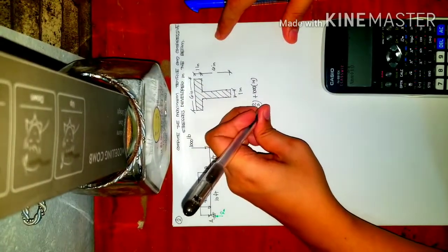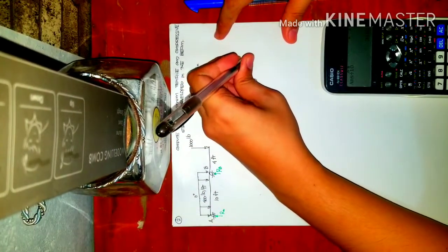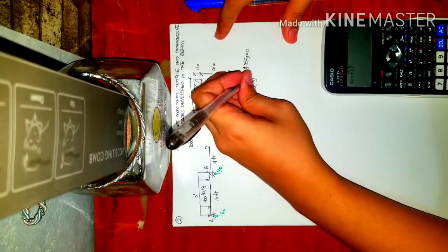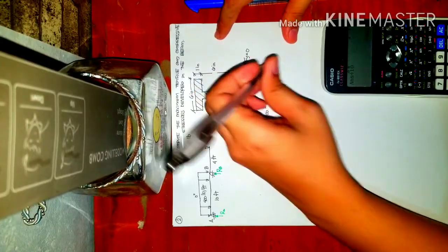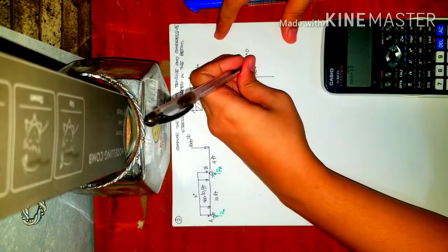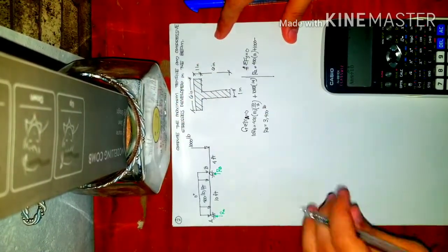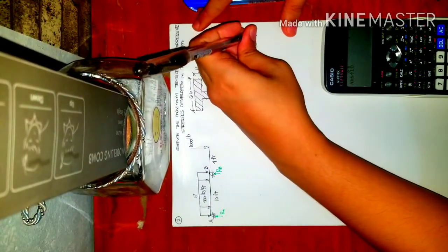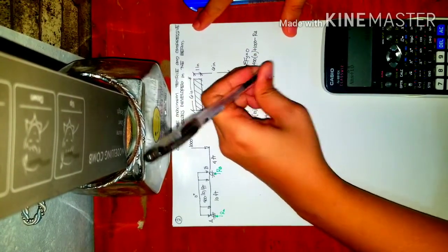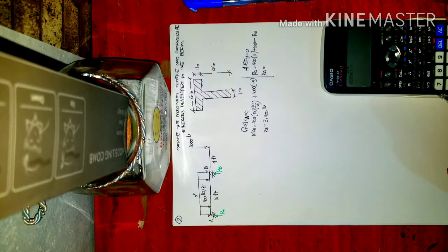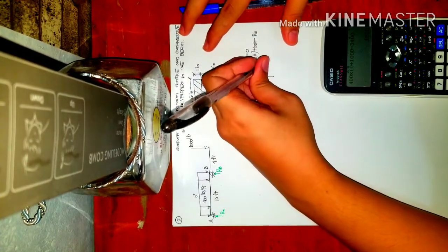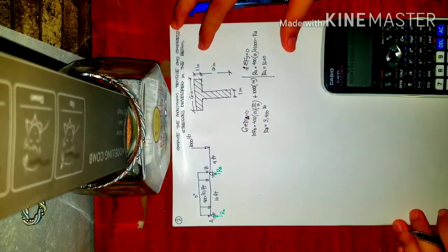So that will be pound, and then take summation of forces ng Y o vertical, assuming upward direction as positive, to solve for the value of your RA. So RA is just equals to 400 times 10 plus 1,000 and then minus the RB. So what is the value of your RA? 400 times 10 plus 1,000 minus 3,400. So that will be 1,600 pound.